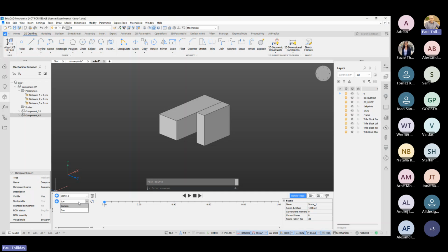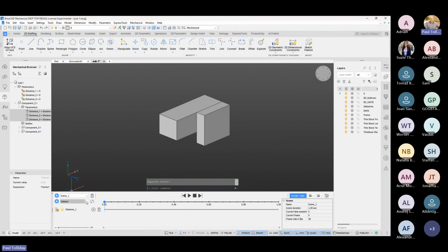And quite often I get people asking me, well, I can't animate or change any of my constraints in this assembly. A very, very simple workflow to be aware of is the parameters of the subassembly or block are displayed under your parameters dialog box, but they're one level down. If we want to access these, we simply select the parameters we want to access, right click and select link to parameter. That will now give you three more parameters at top level with the same name as you had in the original parameters, but now they are accessible to the animation time bar.